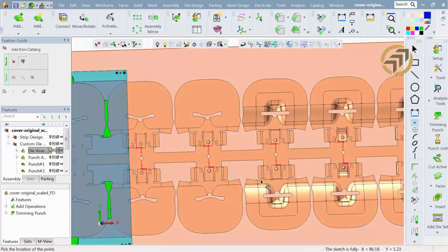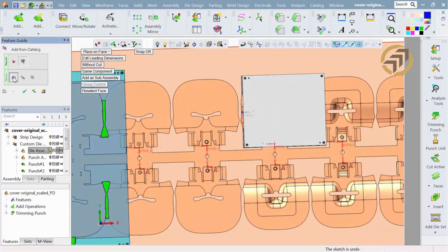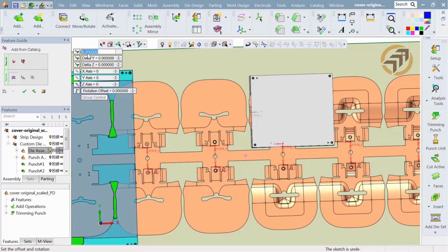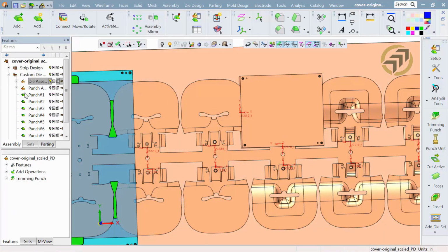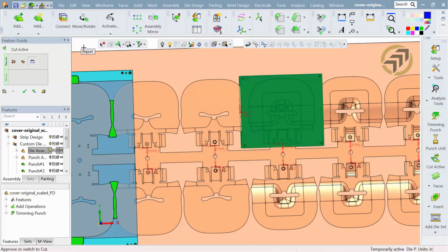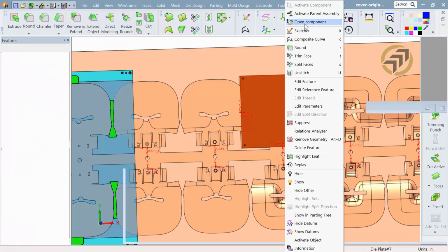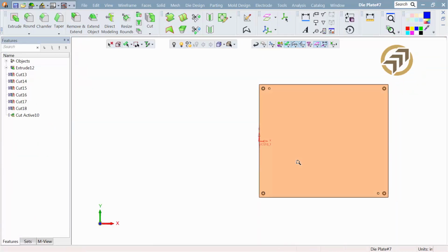And like I said, those units could be punch units, they could be cam pierce units, rocker assemblies, it's whatever you want to assemble together. We'll position that steel to capture that particular station, and I'm going to tell it that I want to grab the information that I've got here right off the strip. So I'm working on the die side, creating a piece of die steel that's going to form that station for me. A lot on the screen, so let's just open up that individual component now.